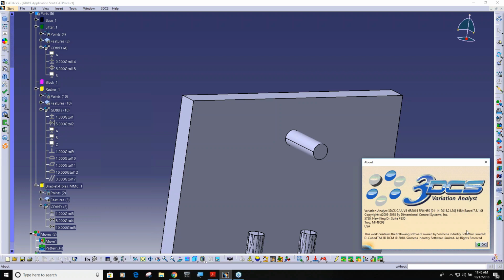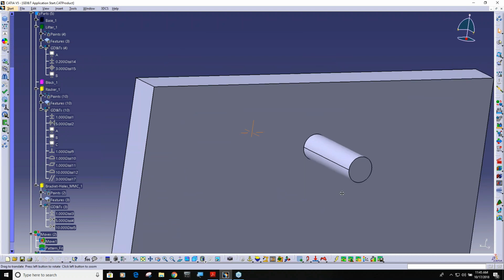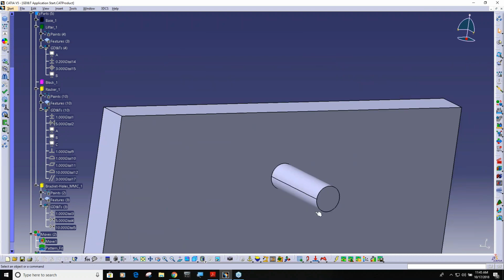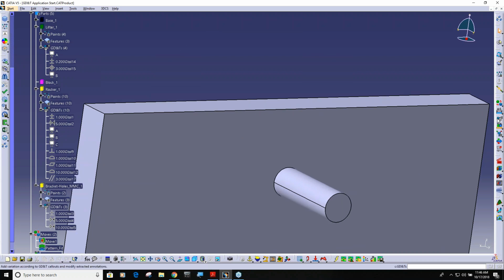That's correct. And the other thing that's key to note is that we did add the whole capability of using GD&T and datum reference frames. You saw me put perpendicularity on a surface with no datum reference frames, and it's still tipped and rocked. It's just tipping and rocking from nominal. It has no connection back to a surface that could have a tolerance.